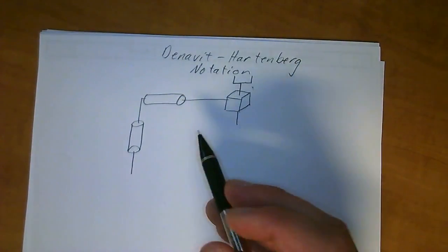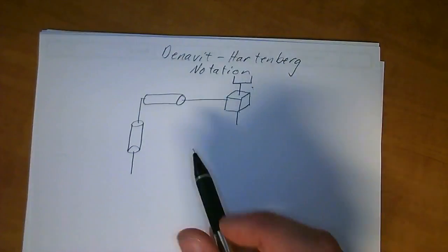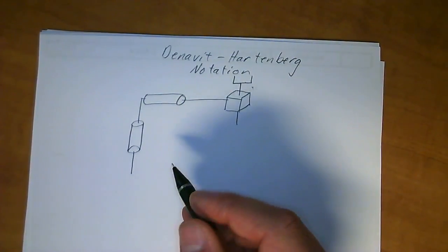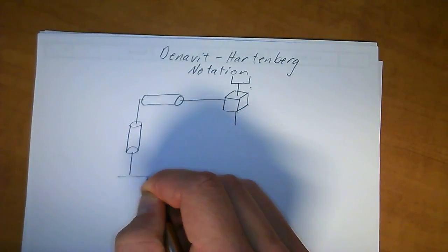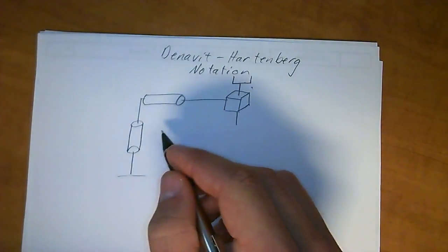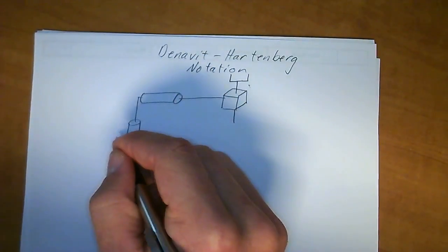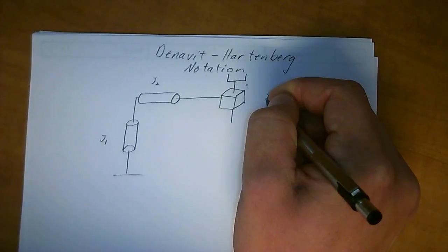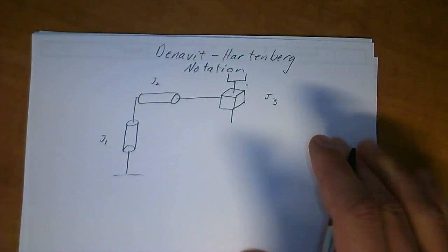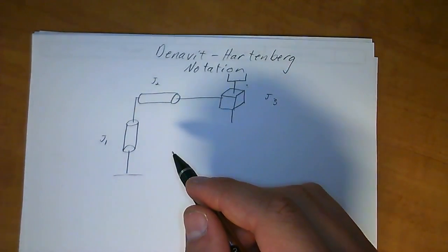So the real secret to DH notation is how you define the axes. Usually what you can do is start out, you've got a base down here. You have to define the axis of each. Well, actually, before we even go to the axis, let's just name the joint. So this is going to be J1, joint 1, J2, and J3. Make sure you point them out to the side because it's going to get really crowded in here pretty soon when we start drawing everything